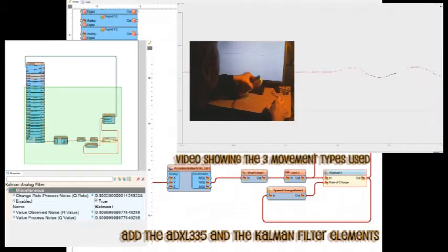This video up there shows the three different movement type samples that are used. One is with the bottom stationary and the head tilting forward and backward. The second one is the bottom and the top moving in the same direction at the same time, same speed. And then the top is stationary with the wheels moving back and forth, which is what an inverted balancing robot does.